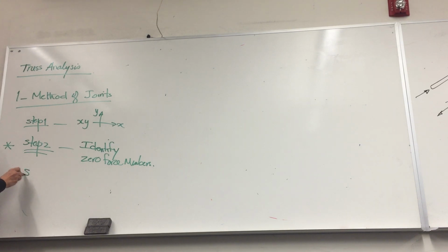Okay? Step 3. In frames, you start with breaking the entire structure apart and drawing the free body diagram of each piece.